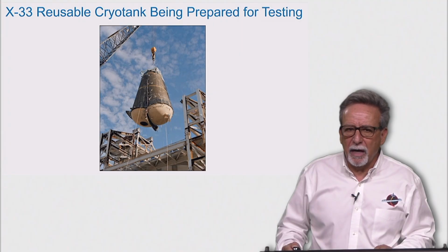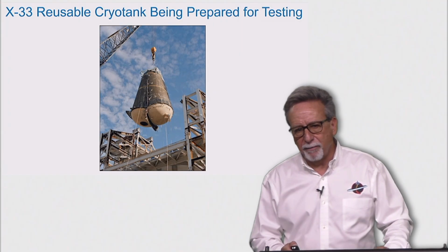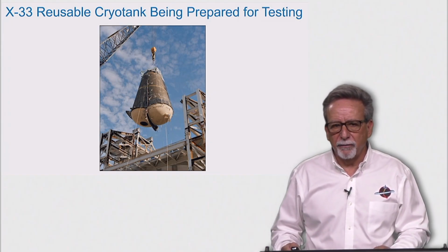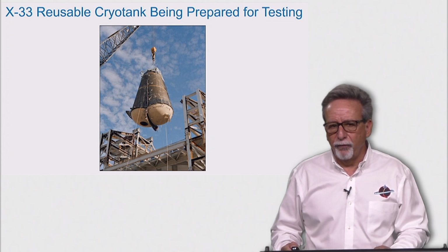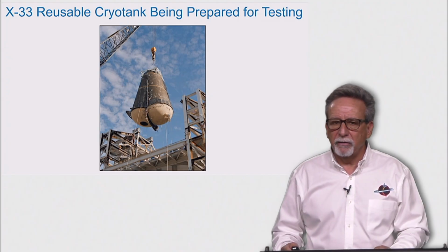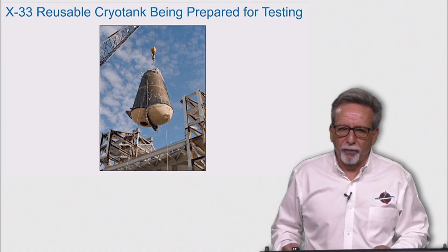Lockheed's concept did not follow the building block approach which we outlined as part of the ICE methodology. They did not explore all potential failure mechanisms of the cryotank prior to designing their full-scale test article, which you see here. This full-scale test article was to be their proof of concept test. It was large, it was expensive, and it was difficult to manufacture, and as a result, the final design of it occurred late in the product development part of the program.